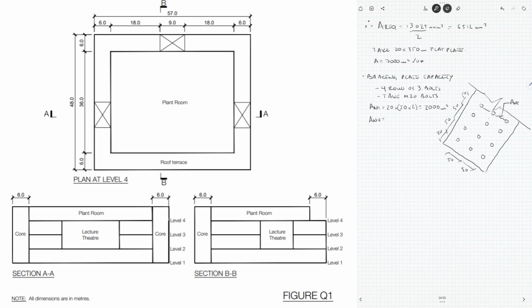Even though the cross bracing is a typical element, like a column or a beam in any structure, I focus on checking the capacity of the connection. As a result of the high wind loads, you'll have high forces in your bracing, and the connections to them tend to be the weakest points, and that's because the connections tend to be done by a flat plate, regardless if it's a flat cross bracing or if it's a circular hollow section. The connection to the bottom or to the corner of the column tends to be via flat plate.